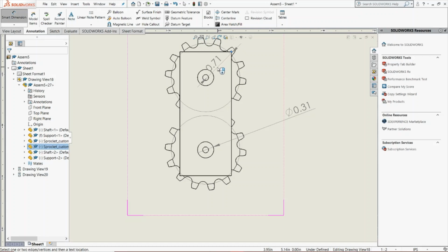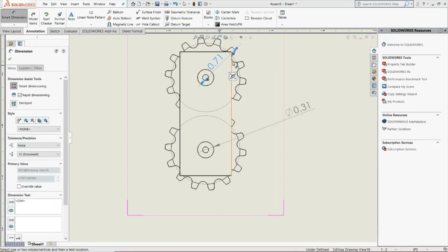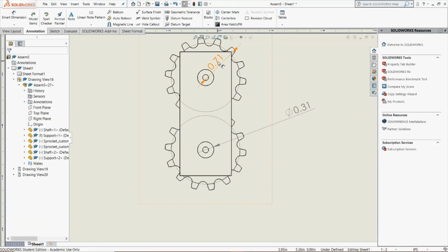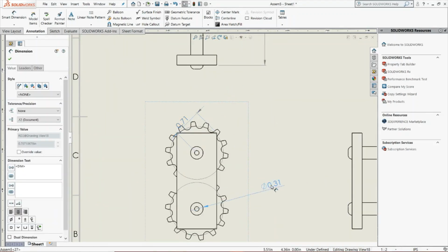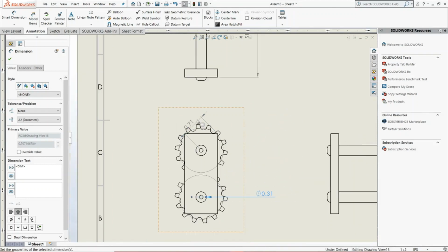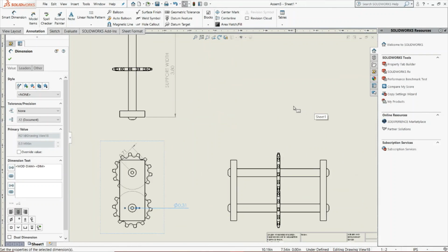So this is the minimum length. Meanwhile, this is going to be our vertical length if we had a right triangle. Again, it really comes down to where you want to put your dimension. You could also drag them around. So say you're not happy with the position, you could just move this lad around wherever you want and declutter your drawing to some degree.